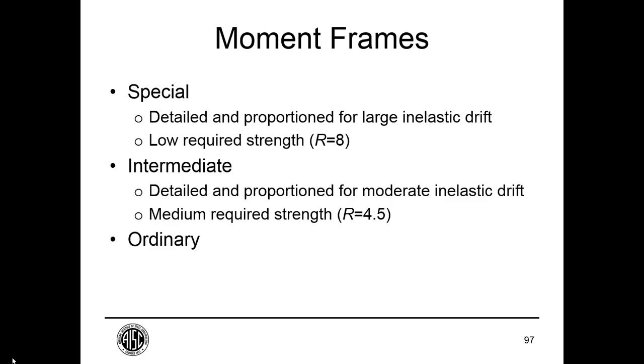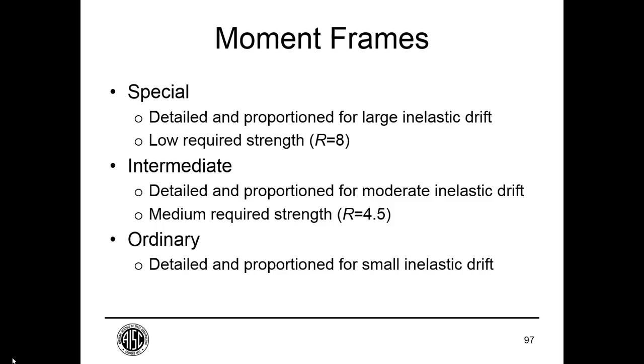And then we have ordinary moment frames. They are detailed in proportion for relatively small inelastic drift. And they're given an R factor of 3.5. So they're designed for quite a bit more than the other systems.